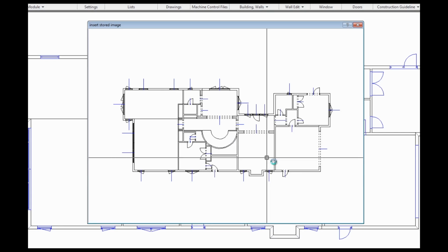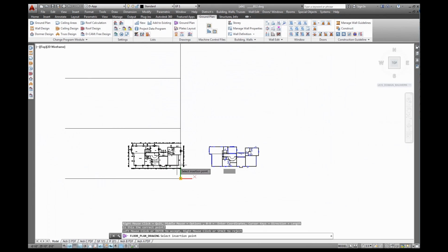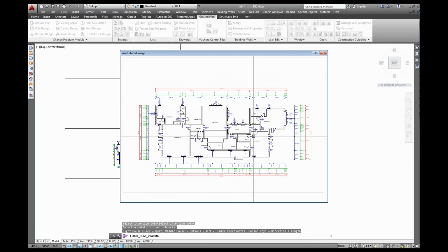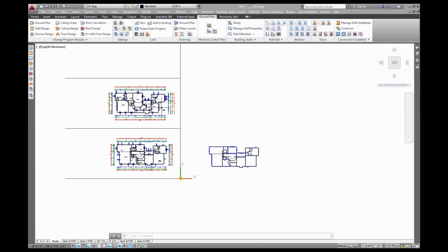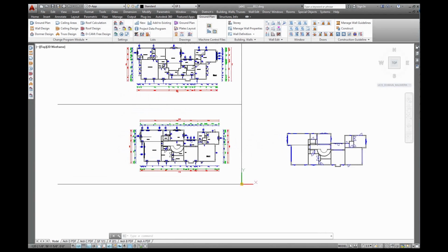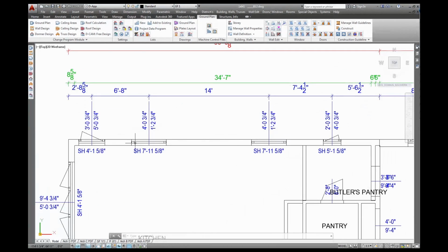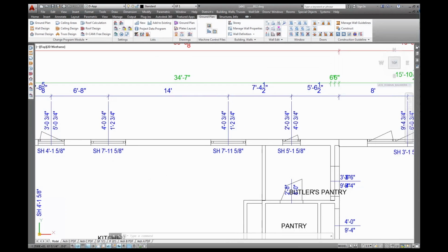So there's my 2D drawing. I just grab that here at the corner and put it right next to the 3D model. Drop it there, text box, and that's my second floor here at the corner, and move that up here in that area. Text box for that. Okay, this is all 2D drawings now, taken directly off the 3D model. So you can see the dimension lines, window sizes, all automatically dimensioned to my specifications.